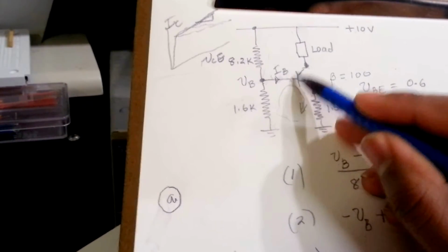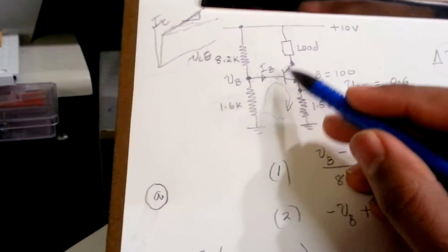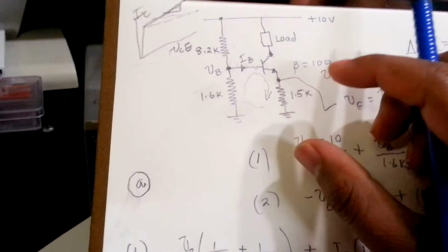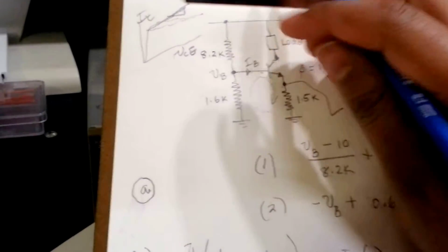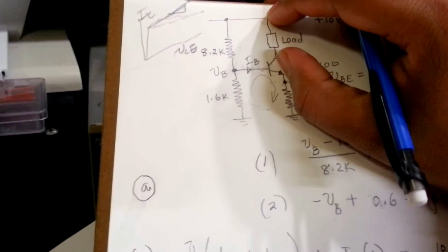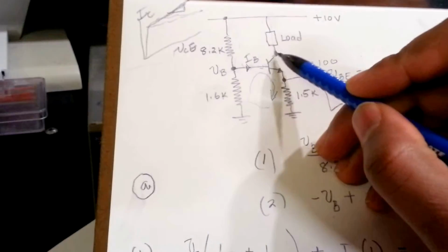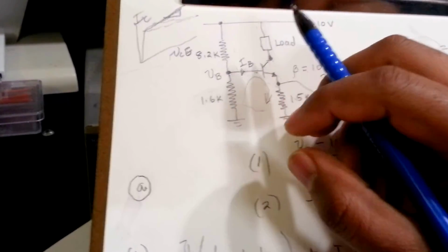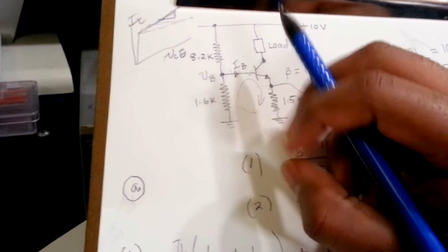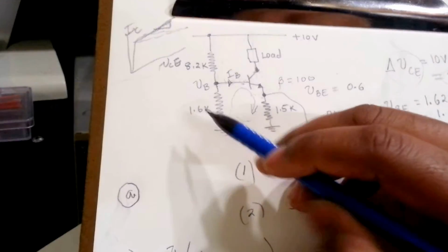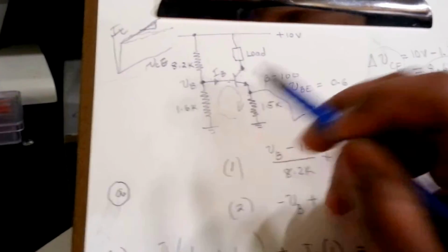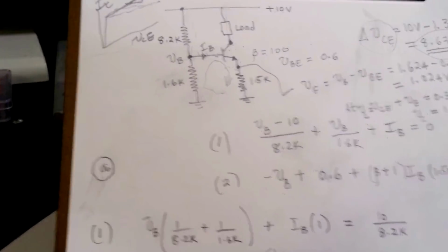That output impedance is related to the change in the collector to base voltage, and it relates to the internal structure of the transistor. It's called the early effect. When there's a change in the compliance voltage here, the collector to base junction width will increase and decrease, and that width change is manifested as the output impedance of the transistor. So that's the other effect. The two effects are the beta change and the early effect. Those are the two effects that the book is talking about, and these two are very important.